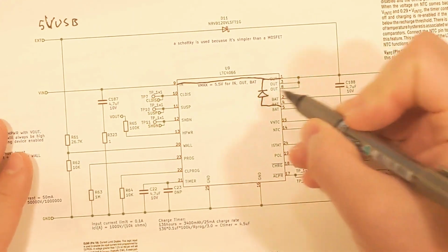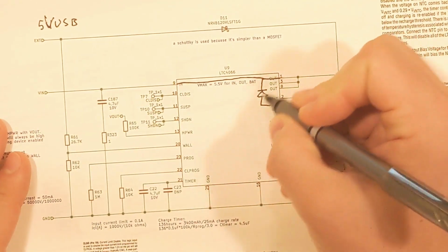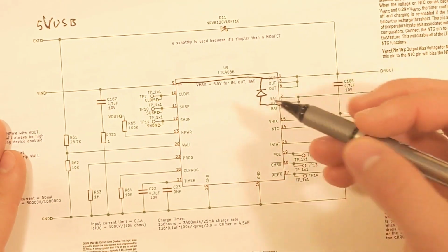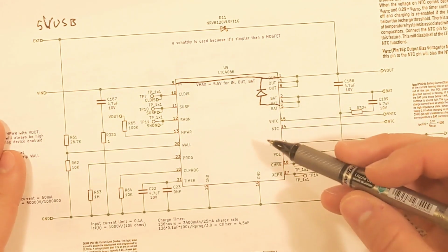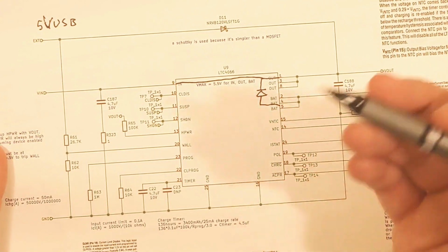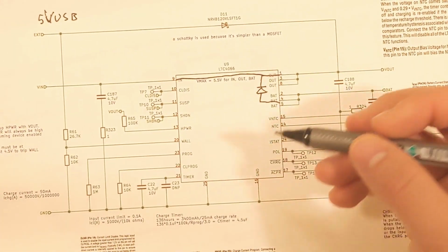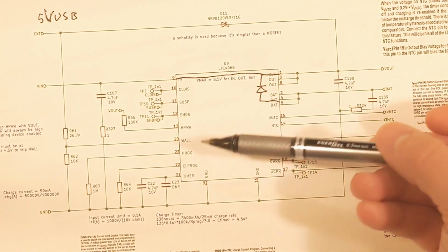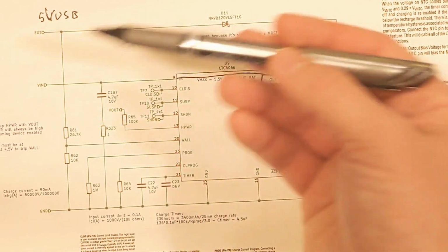It also means that the current from the input can be essentially combined with the current from the output. This will allow me to use as much solar energy as I can and essentially not use the battery unless I absolutely need to. Most of this circuit here is really just Rs and Cs to set up the proper usage of this chip. Up at the top, I have the 5-volt input that you saw from the other page.